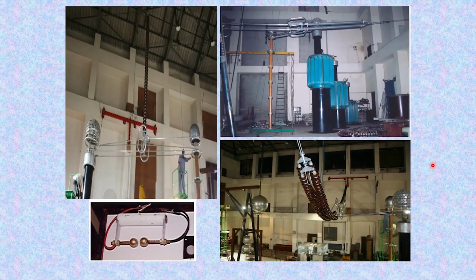These are the mounting arrangements for various configurations. This is the sphere gap arrangement, a small sphere gap of 2 centimeter diameter, and the spacing of the gap could be 4 millimeter in this case. There is standard breakdown voltage information available in the standard. This is measured as per the breakdown, then converted to laboratory conditions, standard temperature and pressure, and it will be connected across each disc.